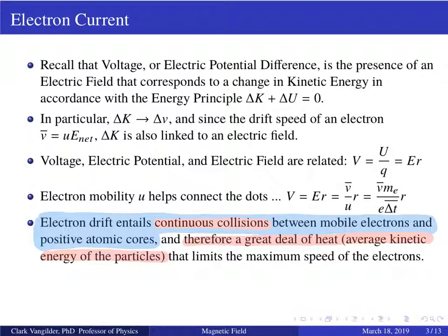Right? So if you've ever put too many extension cords together, you'll notice they get hot. Or if you're using, say, a weed whacker or a leaf blower and you don't have a high gauge, a really thick cord, you're drawing too much current through a thin cord, it gets hotter faster.